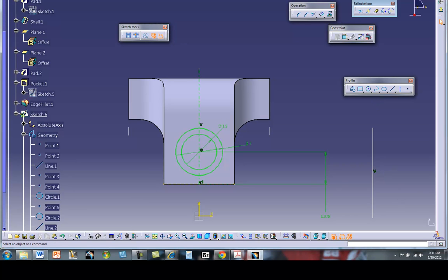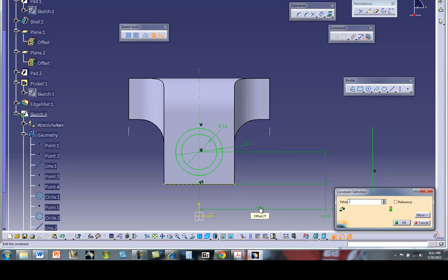Now notice there's not a dimension given on figure 4.97, so you have to give that bottom a size. So first off, I'm just going to drag this line, well, I'll make this line right here parallel to that axis. And now I'm going to give a value from the axis to this line right in here. And let's make that maybe 0.25.